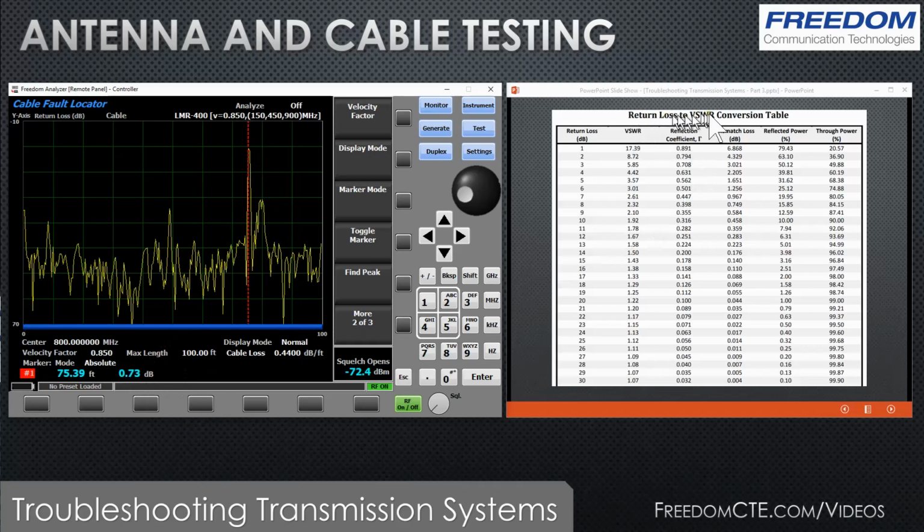So if we look over here at this return loss table, return loss of less than 1 is showing that we're reflecting almost all of the power. And in fact, I've got the end of this cable open, so all of the power should be reflecting. And so we see here in this case that the cable end is open and we're reflecting.